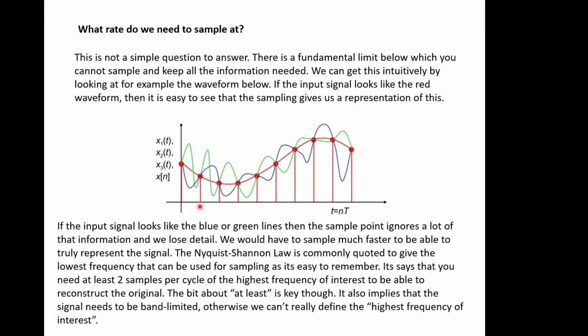And so you don't necessarily need an anti-aliasing filter for audio systems, because the microphone, for example, is the filter. It doesn't respond to higher frequencies. So as long as you sample at twice the bandwidth of the microphone, you don't need an anti-aliasing filter.